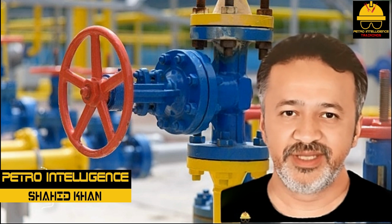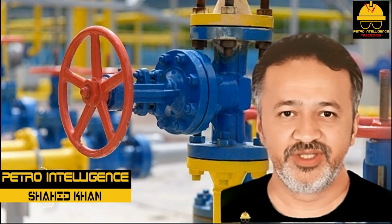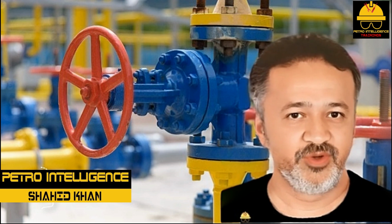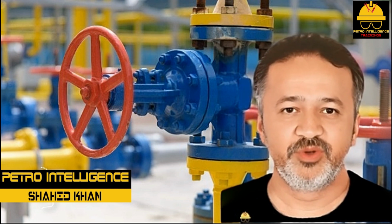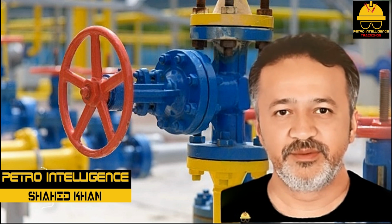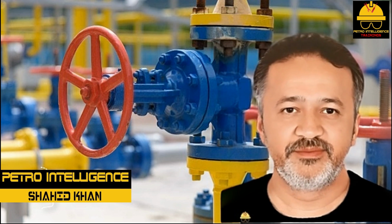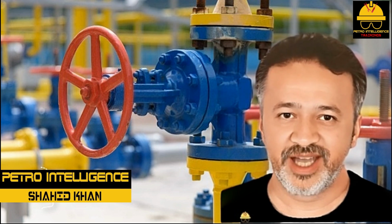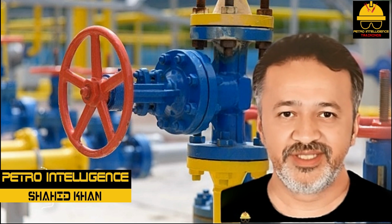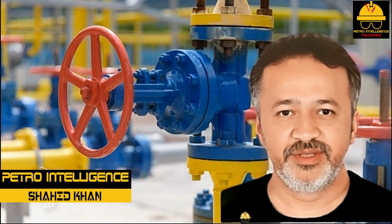Some valves have movable metal gates, balls, plugs, diaphragms, discs, needles, or even butterfly-shaped elements. Most valves are named for the type or design of the flow control element. Valves that are used for isolation are classified as block valves. While gate valves are the most common valve used for isolation, any valve can be used for this type of service. Another term associated with valve operation is valve capacity. Valve capacity is a term used to describe the total amount of fluid a valve will pass with a given pressure difference when it is fully open.